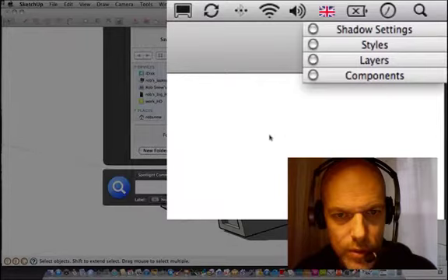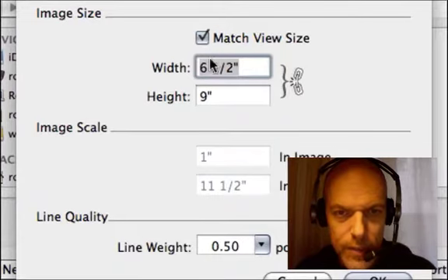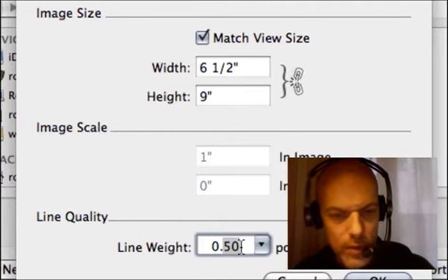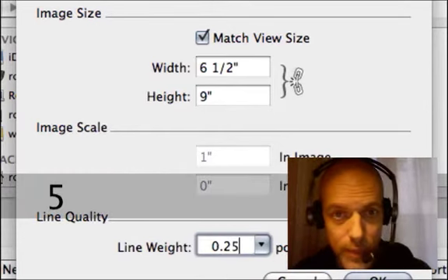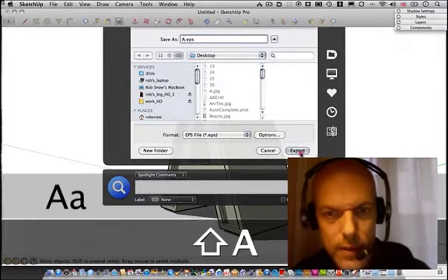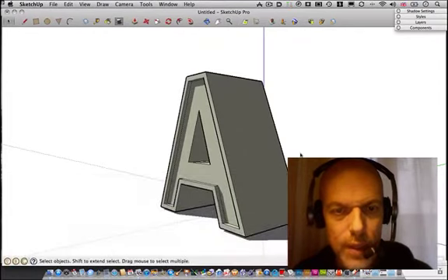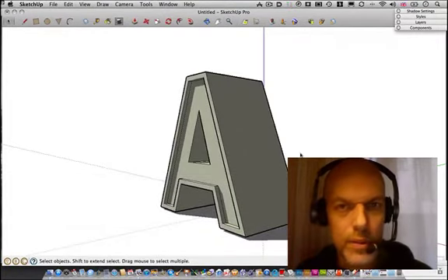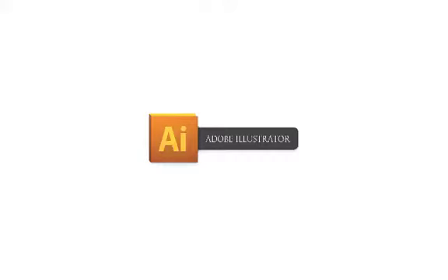That's that. You'll notice you've got options on the EPS. What we want to do is to keep the point size quite small, so I'm going to put it down to 2.5. I think that's the minimum. Okay, and press OK, and then export it. Let's make sure I call it A, like so. Now that's what we need to do inside SketchUp. We're going to bounce into Illustrator now, and I'll do the next part.